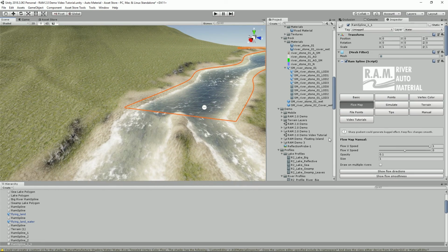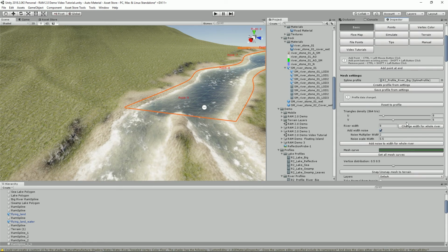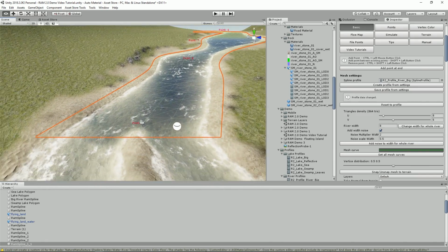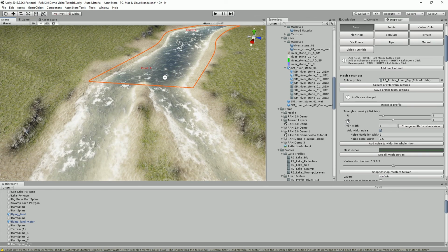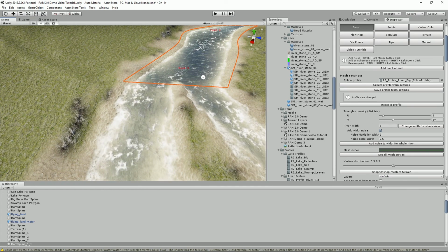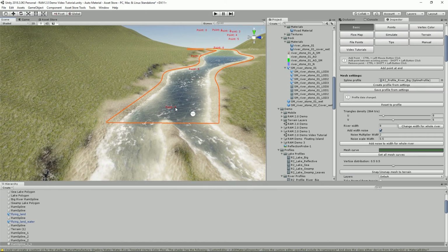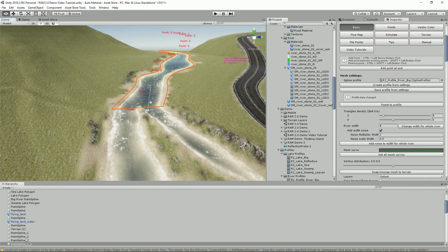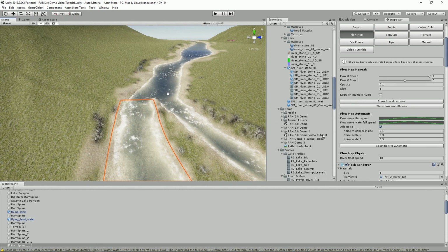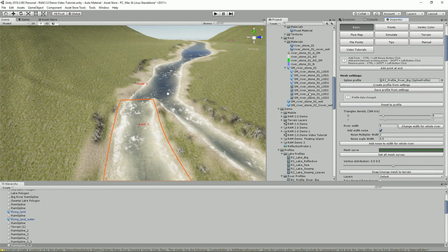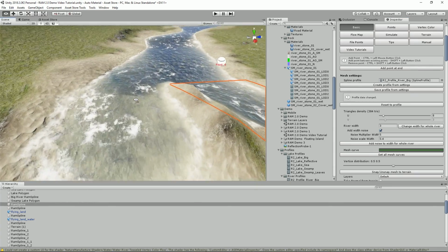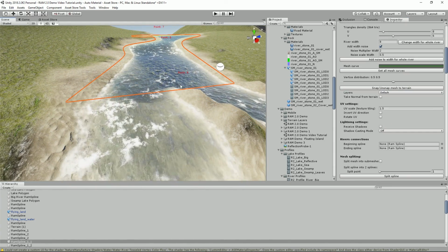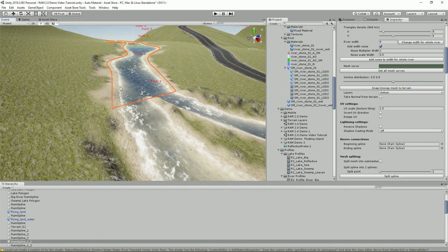This one is more difficult because you have a mother river and its child. First of all, you have to keep some V resolution on your river, because you will split the mesh by this V value into two surfaces. It's very important to have a bit bigger value. For example, here from 6 we have 3 and 3. It's very simple to disconnect one river into two new rivers.